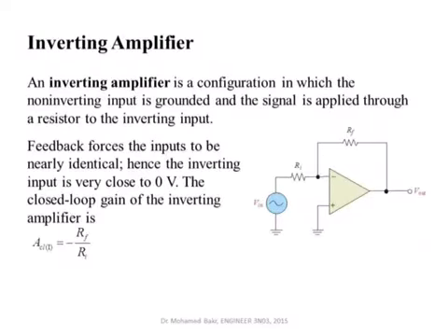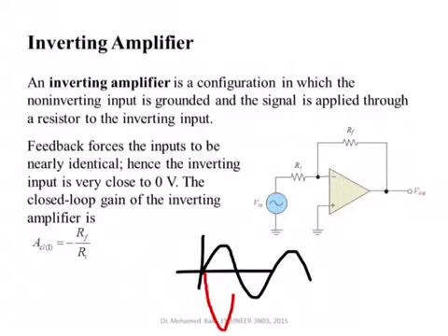One other circuit we see very often as well, and I explained this one in one of the examples earlier, so I'm not going to go into the theory of this one. It's called the inverting amplifier. V output is simply equal to minus Rf over Rin multiplied by Vin, so that if the input is a sinusoidal signal, the output is an amplified sinusoidal signal, but with a phase shift of 180 degrees. So if this is your input, then the output will look something like this one here. It will be a phase shift of 180 degrees but it's an amplified version of the input.